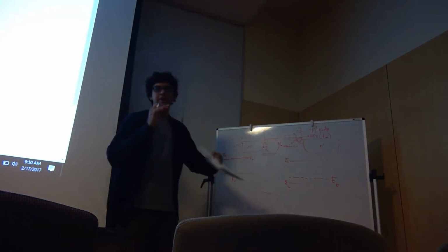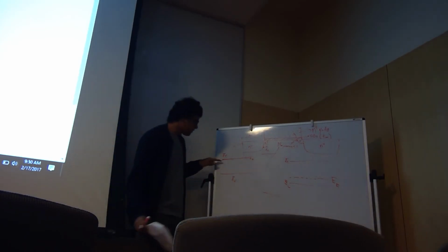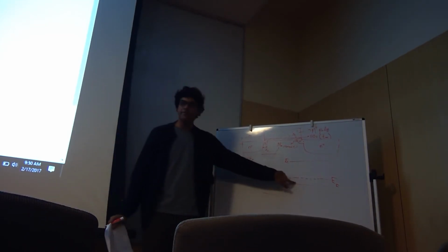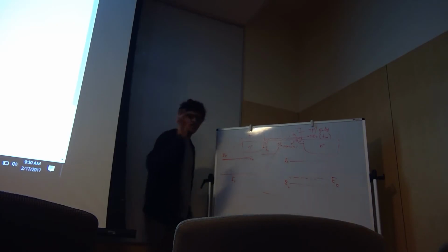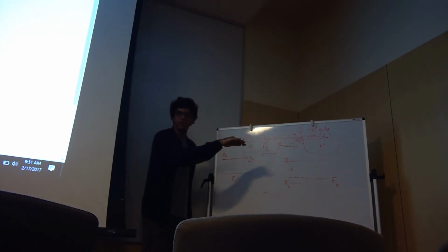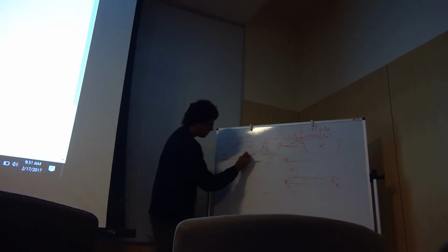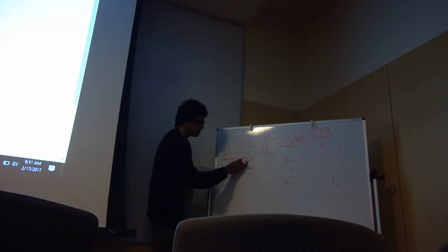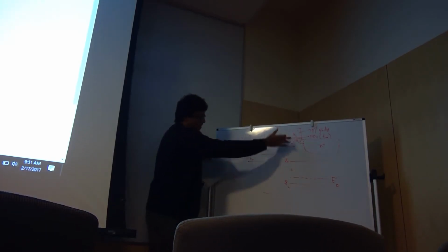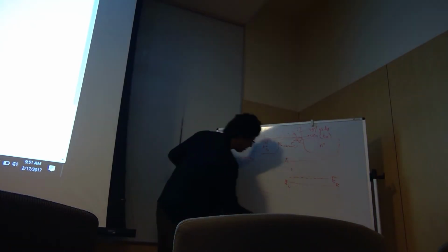Now you can think of Fermi level as something that determines where your electrons will actually go. Because the Fermi level here is higher than the Fermi level here, your electrons, you can think, this is not how it actually behaves, but you can think of it in this way, will generally go to the lower energy level. So you would have a buildup of electrons here and a decrease of electrons here. So if I now join all these together, the band diagram will end up looking like this.